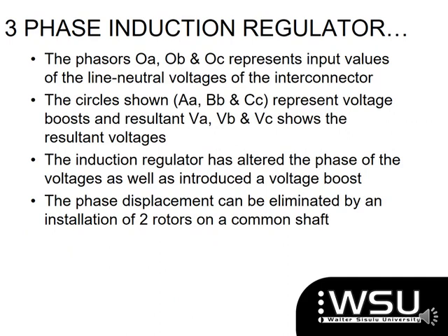So this slide is still talking back to that picture, but I want you to concentrate on the last 2 points, as I've already explained the first 2 points. These last 2 points tell us that not only was the voltage boosted, but there was also a phase shift, because your V'A and your VA were not just of different magnitude, they were also not sitting at the same phase. One was a little bit behind the other. So once this phase induction regulator has done its work, it not only boosts the voltage at the end to be the same as the voltage on top, but there is also a phase shift in your system.